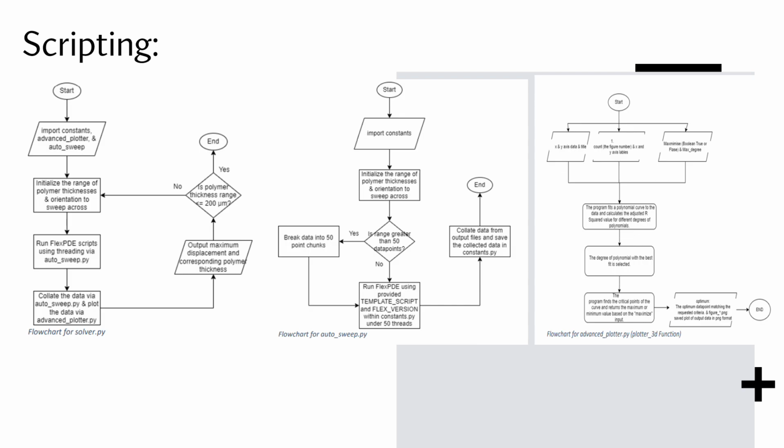The optimization process involves zooming into 5 data points from previous runs that yielded the best sensitivities and using them to span a new range of thickness and lengths. Multiple iterations were done for each material, and the range was progressively zoomed in to a point where it was less than 300 micrometers. The maximum value was marked with a green triangle on the plot, and a legend was added. Curve fitting and identification of the point where the QCM would no longer have an acceptable sensitivity were explored, but not completed within the allotted time.